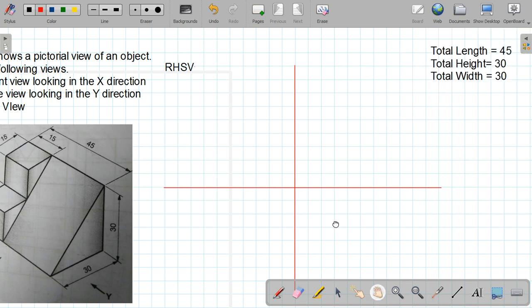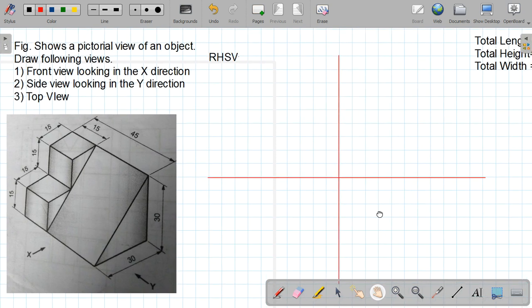So if side view is in second quadrant, then always remember, always we decide first side view where it comes. Once it is decided, now it is coming in second quadrant. So beside that, on top only, in first quadrant now front view will come.